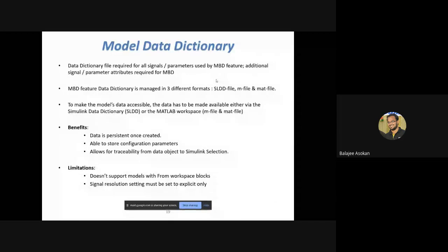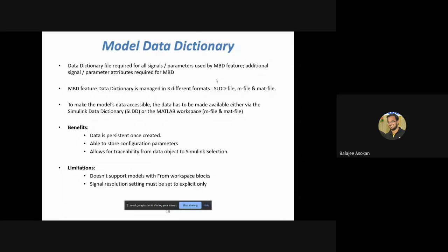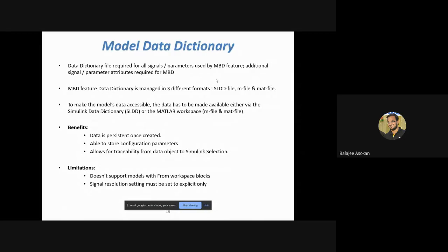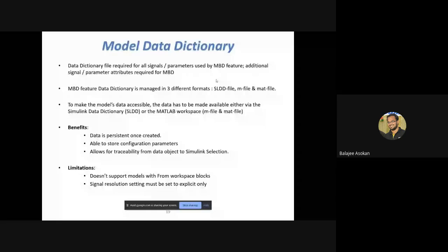I will go to Simulink Explorer. Inside the Simulink Explorer, my Simulink data dictionary will be open. Over there, depending on the type of signal, whether it is a normal signal, a calibration value, or a lookup table kind of value, I will identify that signal and manually enter the value into it. And it gives me the option to choose my data type.